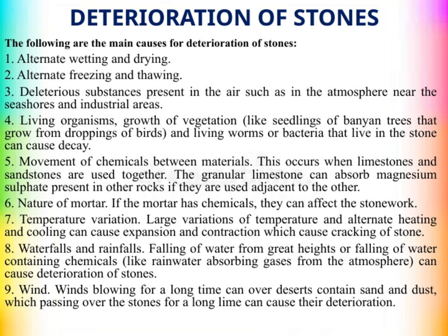The nature of the mortar used in construction matters too. If it contains chemicals, it can adversely affect the stonework. Temperature variation is another key factor. Large fluctuations, with repeated heating and cooling, cause the stone to expand and contract, which can lead to cracking.